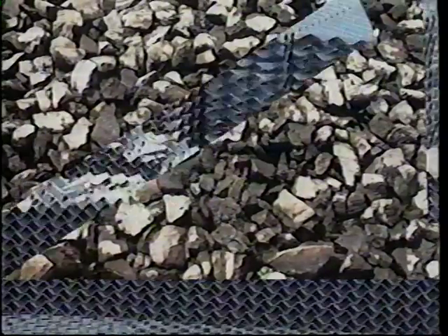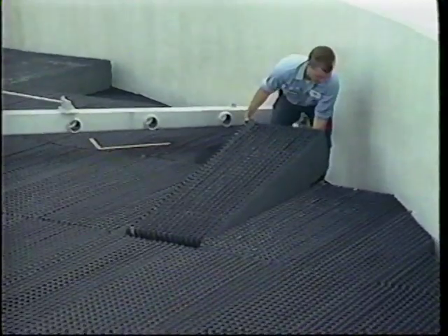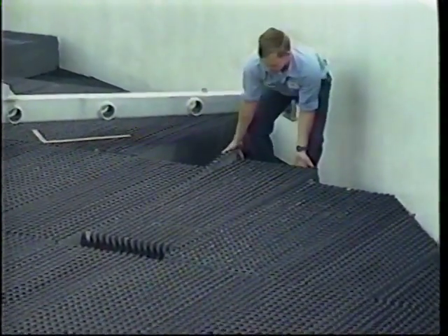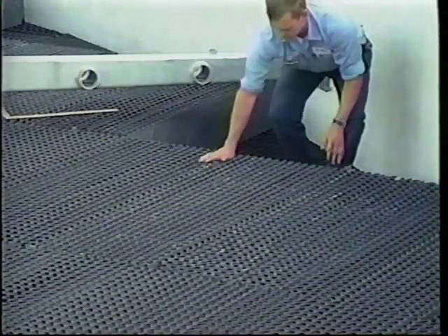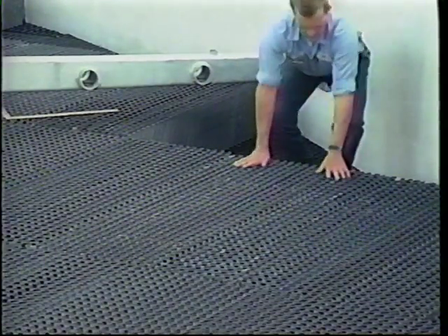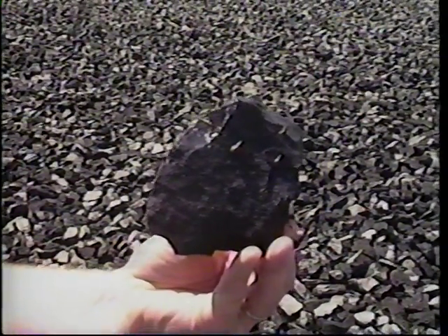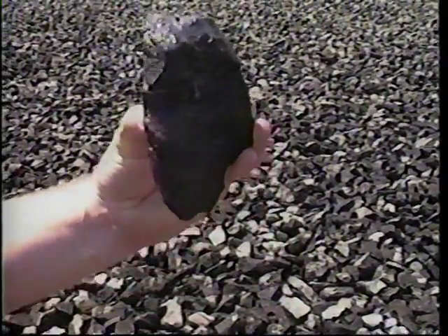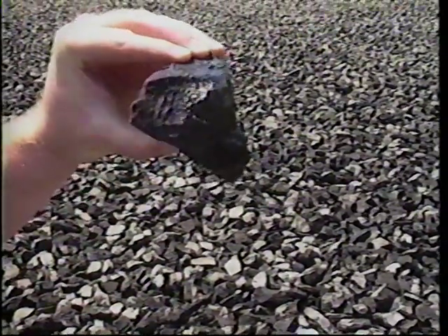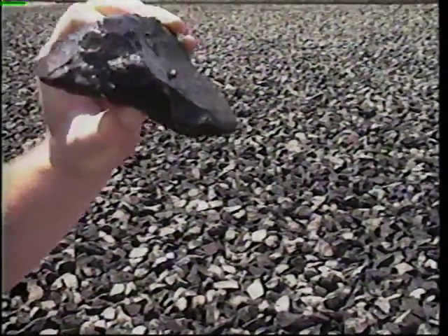Stacked media is generally a plastic media that comes in sections that resemble hay bales. This media is carefully stacked in several layers within the trickling filter. In most plastic media, the top layer has some sort of ultraviolet protection to avoid deterioration due to sunlight. All media should be examined for signs of deterioration. Deteriorating media can lead to poor operation and septic conditions within the filter. The media should also be kept free of debris.